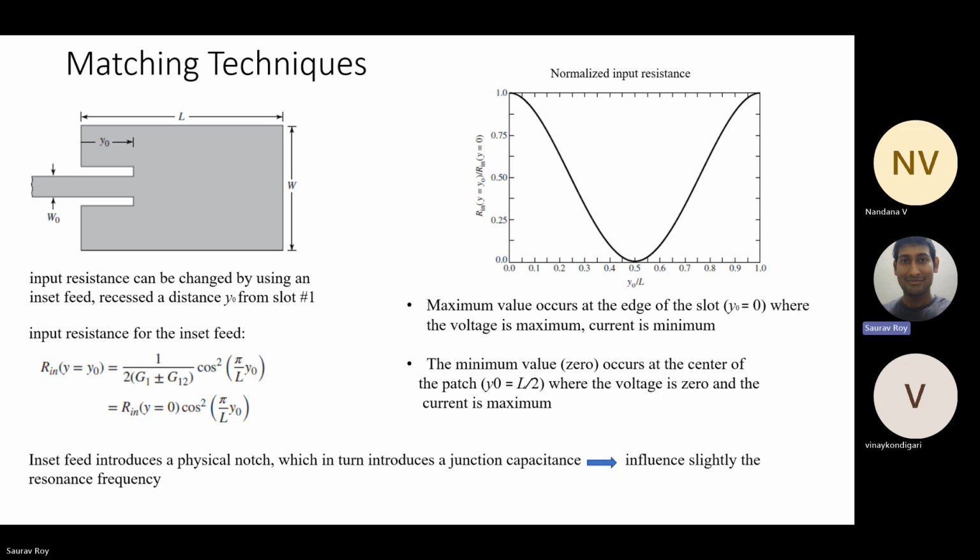So for next week's tutorial, try this antenna with these defined y naughts and different values of this cut. For the junction capacitance, vary how much gap there is, and see how it affects your input resistance calculation. Plot the input resistance by taking a parametric run and see it. Until you do it yourself, you will not learn that much from theory.